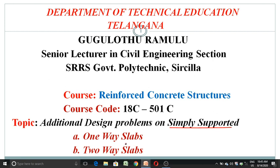What is the definition of a slab? What do you mean by slab? A slab is a two-dimensional element which can be used as a floor as well as a roof cover. These slabs are categorized based on their shorter span direction and longer span direction, that is, one-way slab and two-way slab. The longer span direction I can say is Ly, and the shorter span direction is Lx.